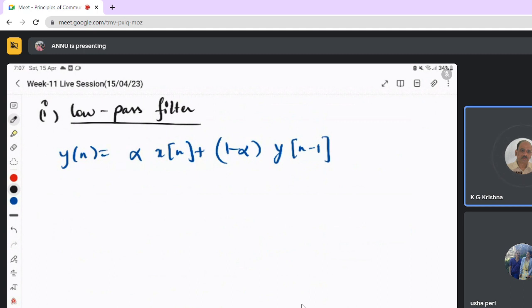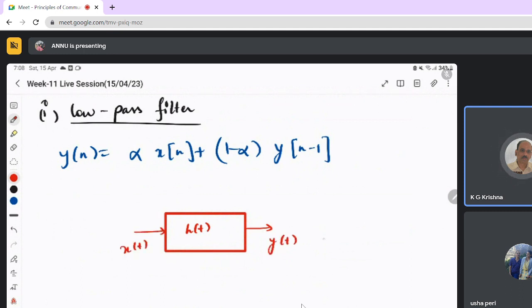Then it is not a system. In a filter, you input a signal and the output is a filtered signal through the transformation of h(t), right? A filter is always represented as an LTI system with h(t); the frequency response of the filter is h(f). In the time domain h(t), in the frequency domain h(f). There is an input signal x(t) and the filtered signal is y(t). So a filter is a system. Anything which can be represented in terms of a transfer function can be called a system.